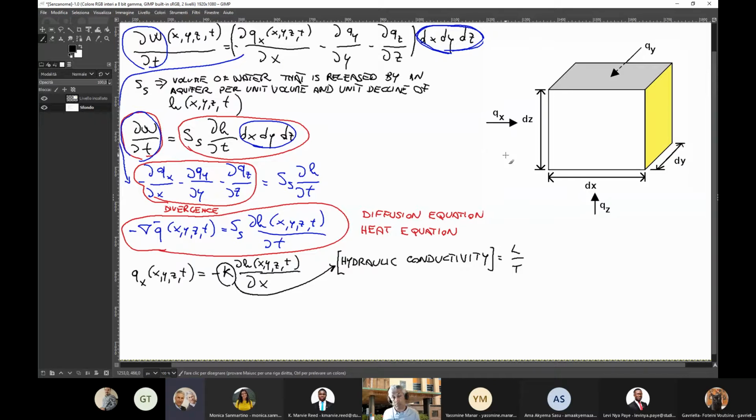And you understand its importance, it's extremely important, because it relates the change in hydraulic head, the change of energy, with the flow. And of course, the higher the K, the higher the hydraulic conductivity, the higher the flow, which means that you expect that hydraulic conductivity is larger for a very coarse aquifer, a very porous aquifer. For increasing porosity, you expect an increase of the flow for the same change in hydraulic head, and therefore you expect an increase of K.